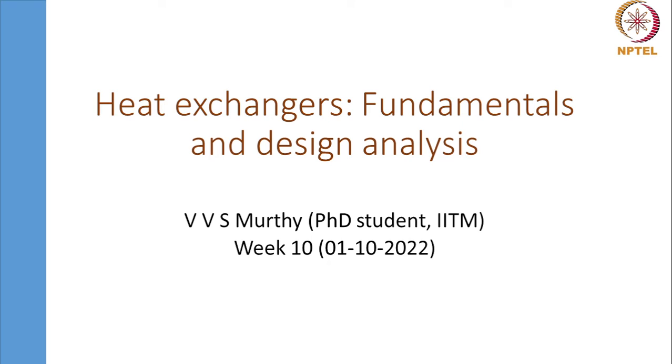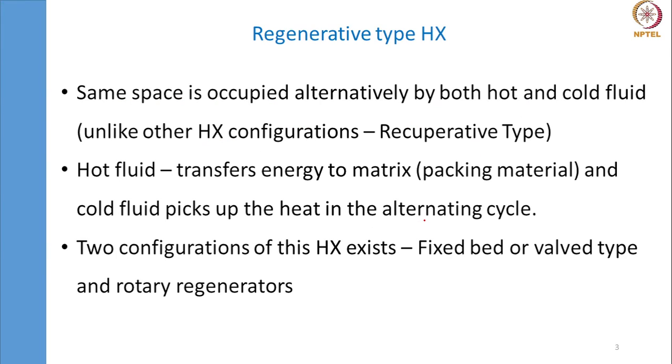Today, we are going to focus on regenerative type heat exchangers. So, we'll first build some background about regenerative type heat exchangers. It is that kind of heat exchanger which is a storage type, and the same space is occupied alternatively by both hot and cold fluids. This is different from the other types of heat exchangers that we have studied. They were mostly recuperative type.